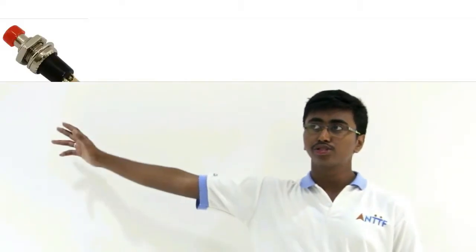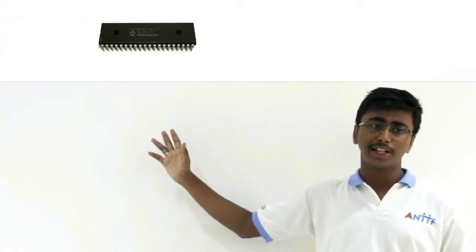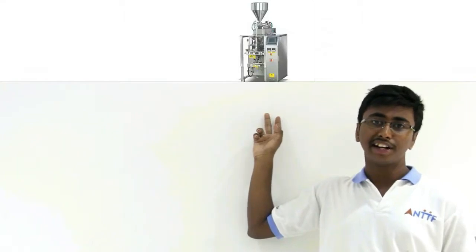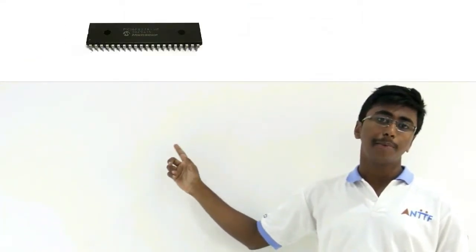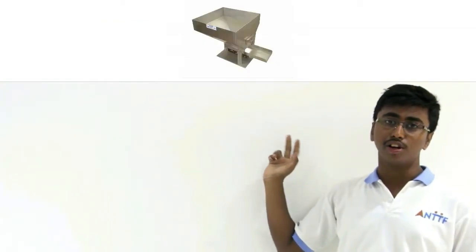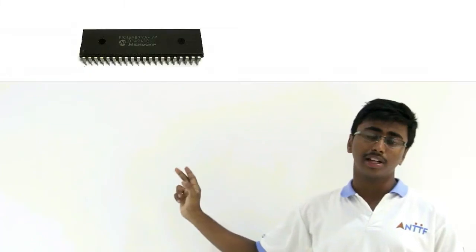Components of our project are divided as inputs, controllers, and outputs. The main control input switch gives a signal to the PIC, and the PIC controls the entire system. Then the two input switches give the input to the PIC, and the PIC controls the hopper. Then the IR sensor gives signals to the PIC, and the PIC controls the stamping machine and conveyor systems. By the program, the entire system is controlled.